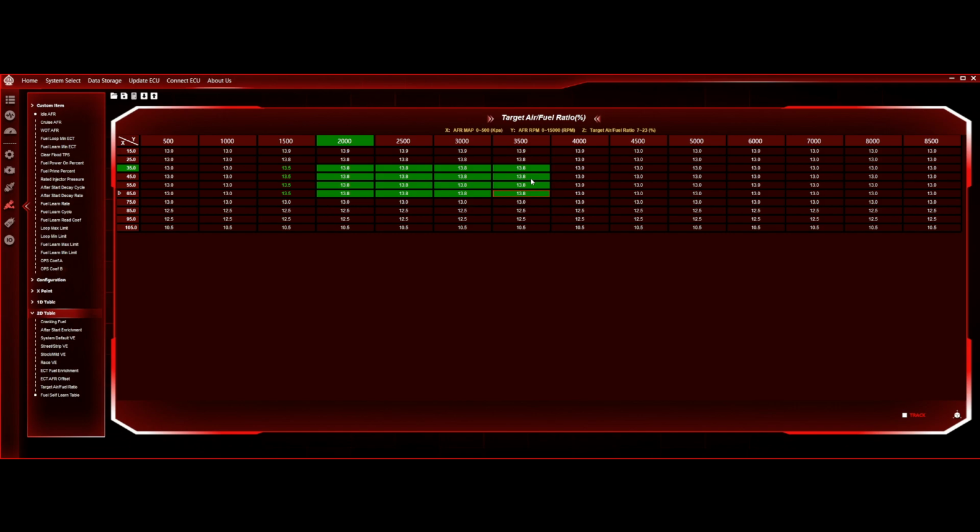A lot of that plays into your timing as well. You definitely don't want so much retarded timing in the low idle areas, because that heats your engine up a lot. You kind of have to figure out where the safe timing advance is for your engine. From what I can tell, for a Bridgeport engine, you don't want any more than 25 degrees of total advance.